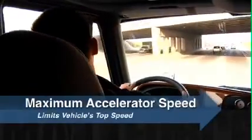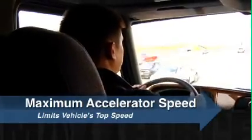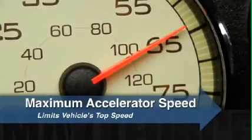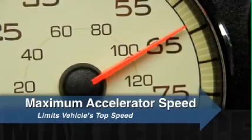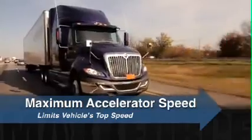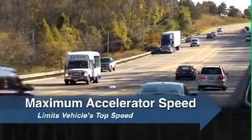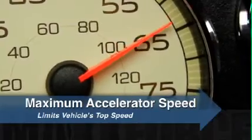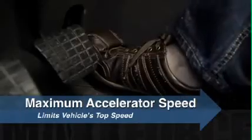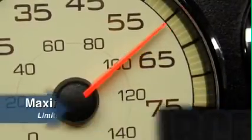The maximum accelerator speed feature limits the top vehicle speed controlled by the accelerator pedal. If your vehicle reaches a certain speed and you have no throttle response, sometimes referred to as a dead pedal, you are probably traveling at the governed maximum speed limit. For example, if you're going downhill and your speed reaches the maximum accelerator speed, you will have a dead pedal until your vehicle slows down below that limit.